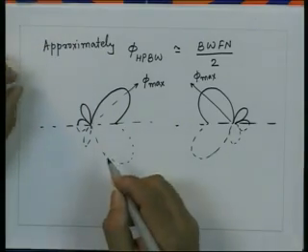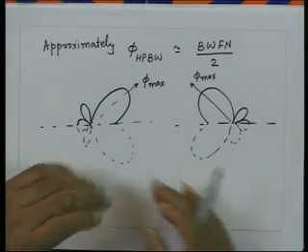So in this situation one can make a further approximation and assume that the nulls are symmetrically placed in the phi domain also, as they are symmetrically placed in psi. As we mentioned earlier, there is a nonlinear relation between phi and psi, so the nulls need not be equispaced in phi.